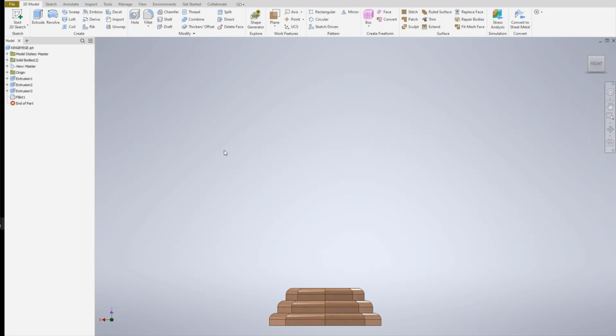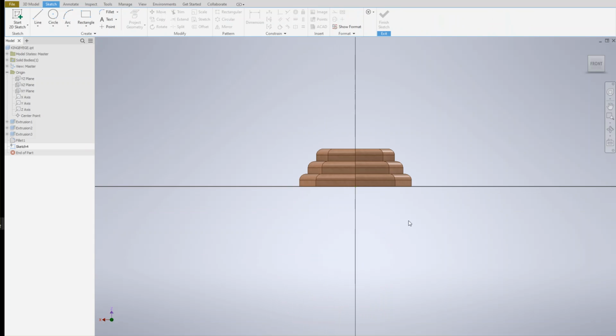What I'm going to do is choose a plane. Go to the origin folder, and I'm checking which plane would be useful to me. Is it the YZ plane? No, it's a single line. Is it the XZ plane? It could be, yes. An XY plane? Probably not. So I'm going to click on the XZ plane. It's highlighted and I see how it's extending. So find the create sketch button on the screen and click on it.